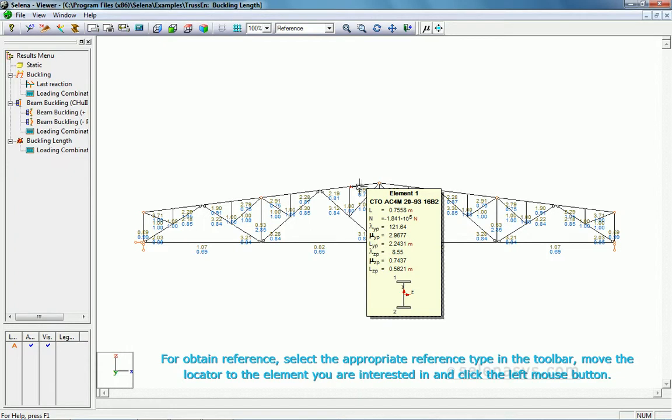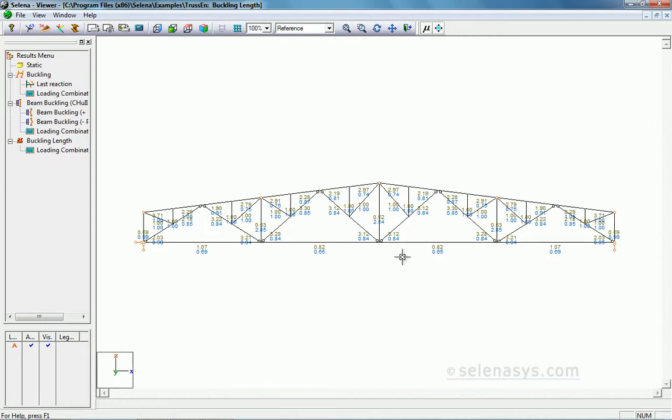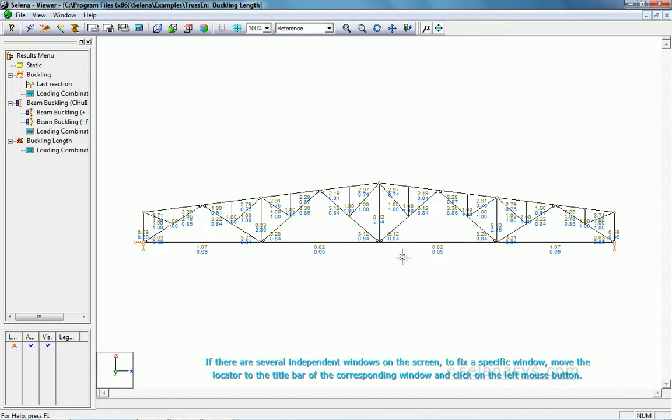As you can see, there are no huge buckling lengths. Moreover, the buckling lengths are calculated even for stretched elements. The buckling length of the rod is determined by the geometric characteristics of the section and the conditions of its attachment. The secret of this analysis is that the program for each rod finds a reaction from the rest of the structure at its attachment points. And it does it absolutely accurately and very quickly. This allows you to set the true value of the buckling length of each rod element.